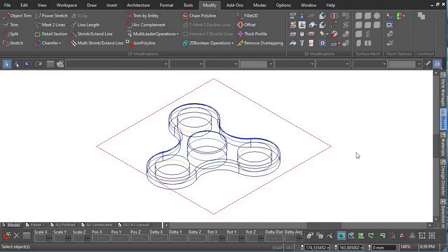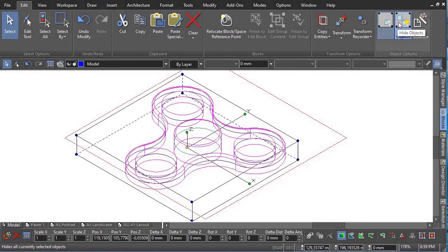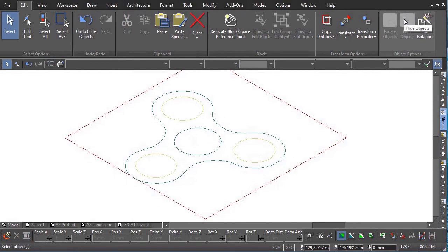The Hide or Isolate Objects feature is available from TurboCAD version 2019 onwards. It provides a convenient method of isolating or hiding an object without using the design director's layer control. In this example, both of the solid objects will be selected. The Hide Objects option is selected, thereby displaying only the sketch geometry in the editor. The two parts will remain hidden until the isolation is ended.